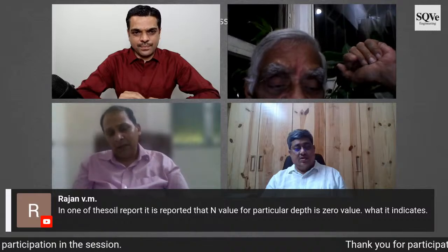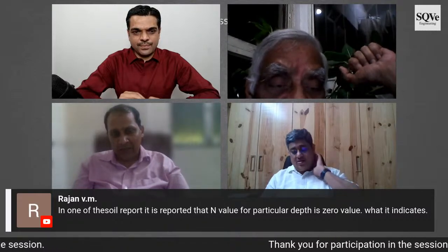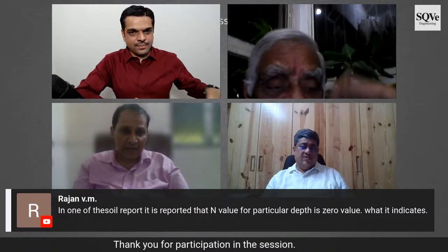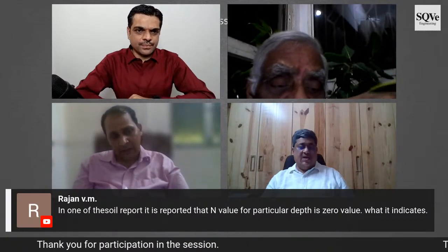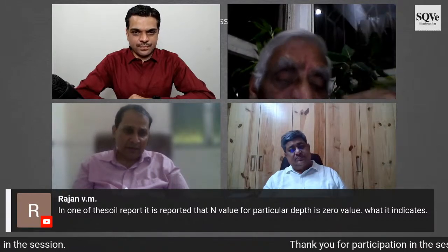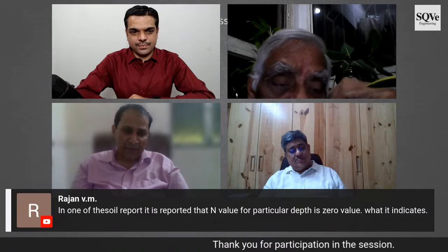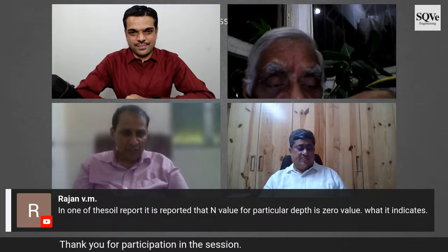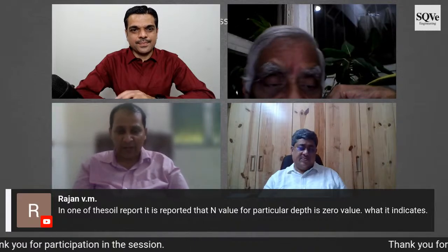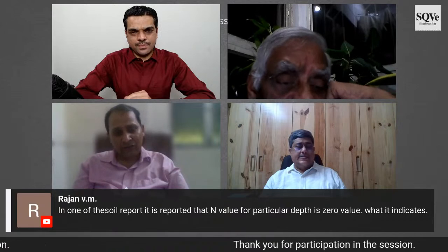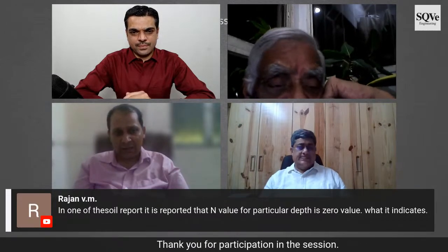This is predominant in the coastal areas in Mumbai, in Uran, JNPT. If you go to the Gujarat side, it's quite common in Kandla, Dahej. It is also common in Cochin. Cochin has about 25 meters of soft marine clay extensively. So these formations are encountered.